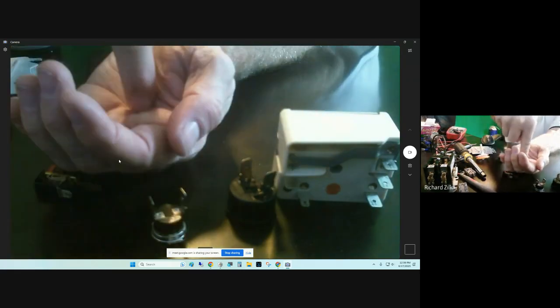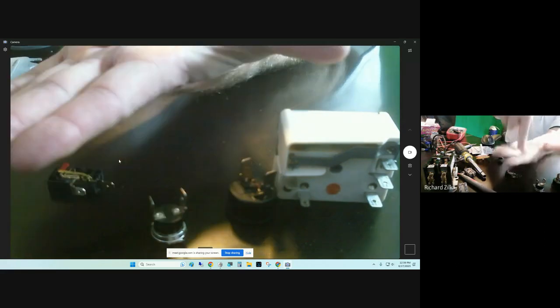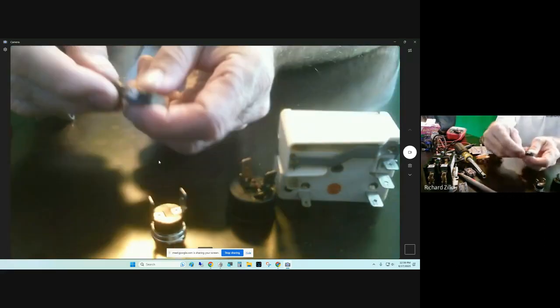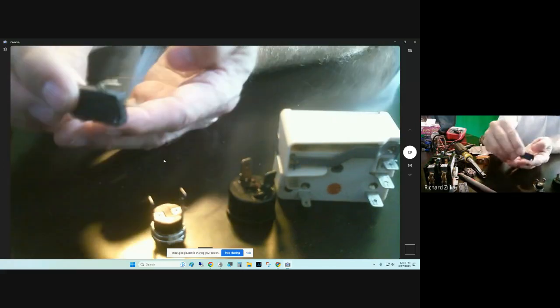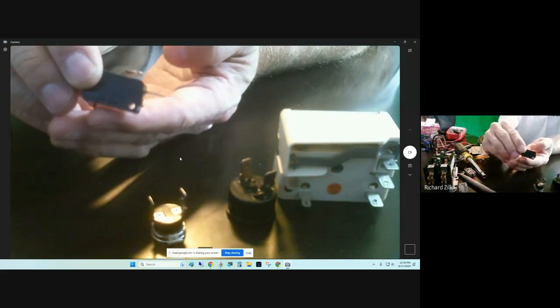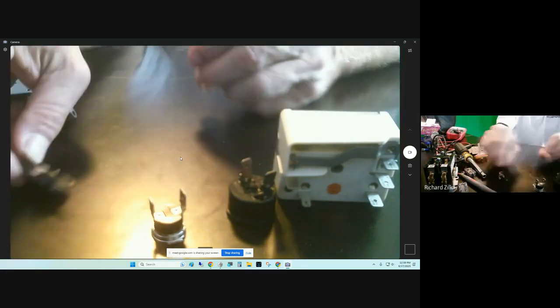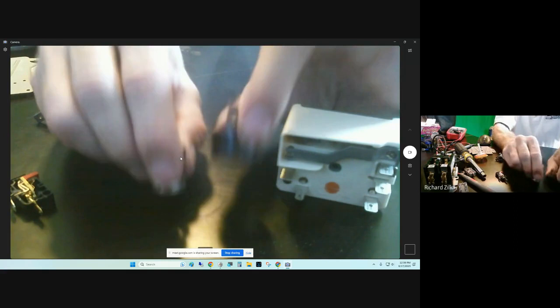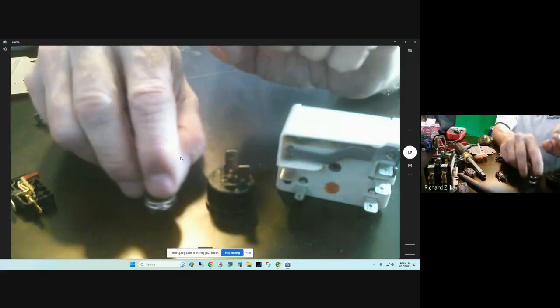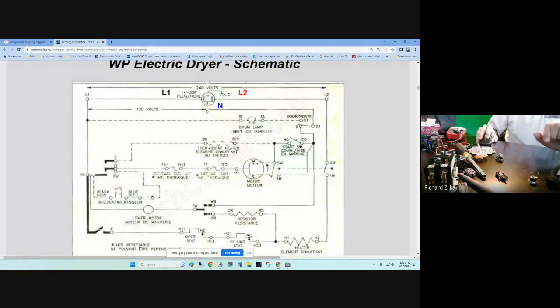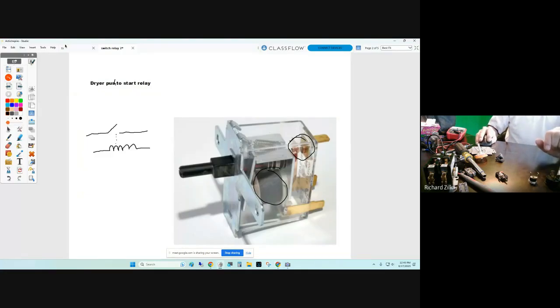And on top is a little pin that pushes the switch up and down, like I did on a door switch or I did on this switch. So imagine that bimetal on the bottom of this here, and when it's heated, the bimetal pushes it up. When it cools down, the bimetal goes away. So these are actual thermostats or bimetals, and I have some pictures to show you real quick, and then I'll go back to this infinite switch here. Here we go. Just got to figure out which screen.